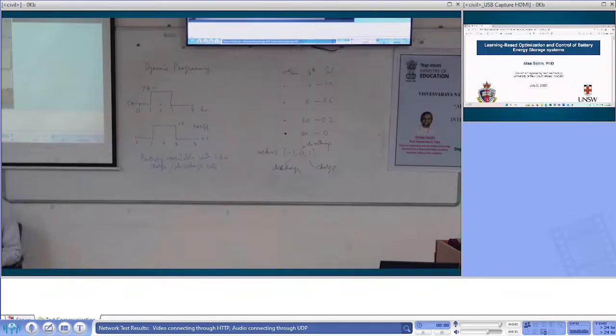I can do 3 things, right? Charge, discharge, or do nothing. If I do nothing, where would my battery be at the end of the 4th hour? I am sitting down there, at 0. What will be the penalty for that? 100. Can I discharge at that point? If I charge, will I reduce my penalty? If I charge, I'll reduce the penalty by 50. So if I'm sitting there, my action would be to charge, go to 50.